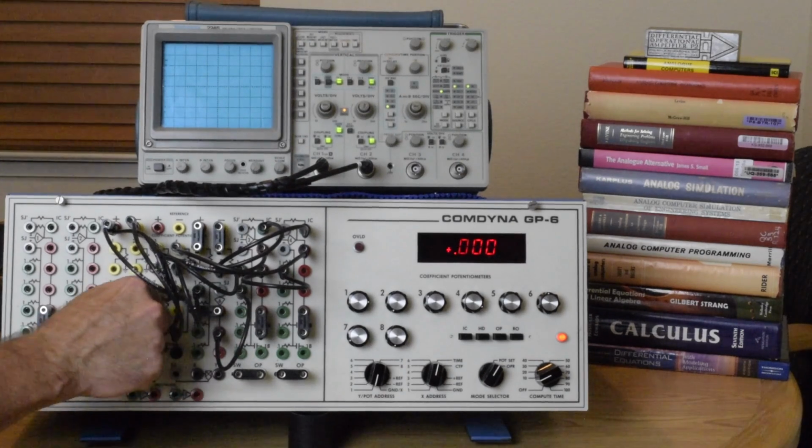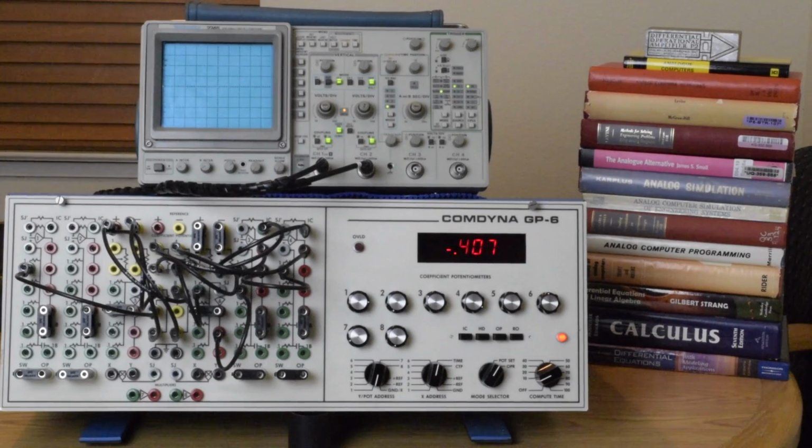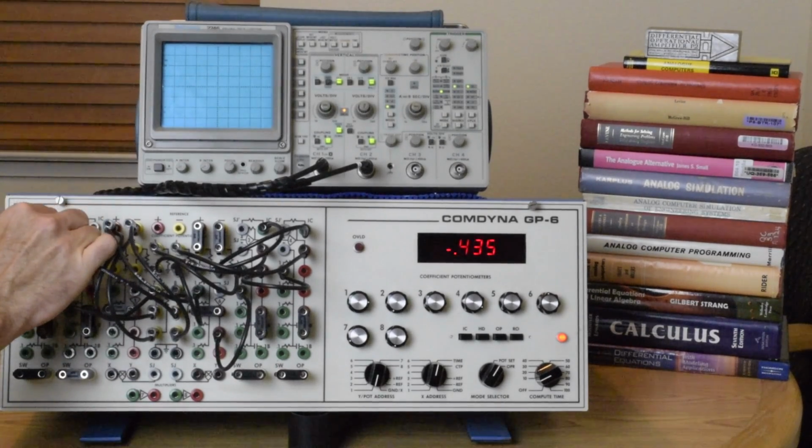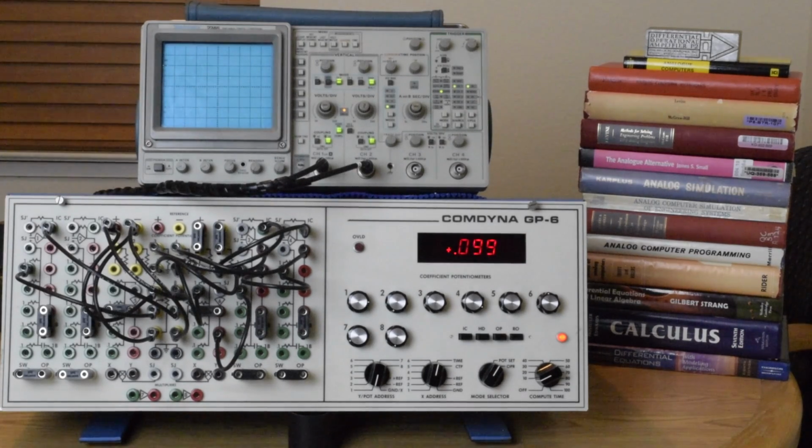So we'll connect that input to the first input of integrator number 1, and then we'll use the second potentiometer, 8 in this case, to enter the constant of integration. So we go from the wiper of 8 up to what we refer to as the initial condition jack of integrator 1. So integrator 1 will always start with this value, and at the output this will effectively be the y-intercept of the solution. So that's all there is to solving that differential equation.